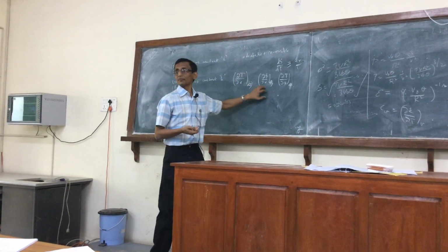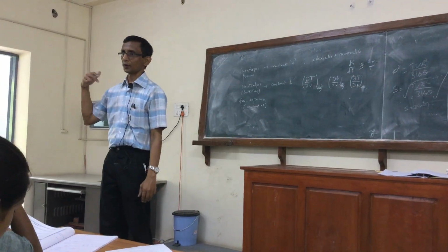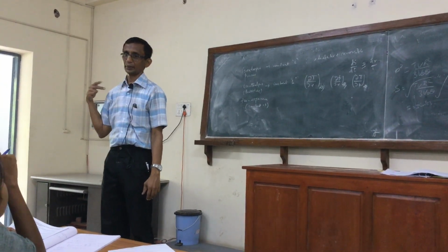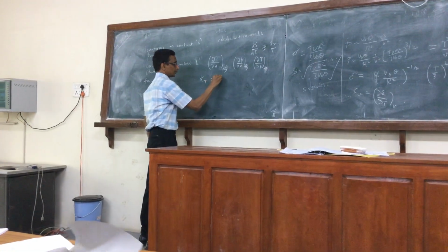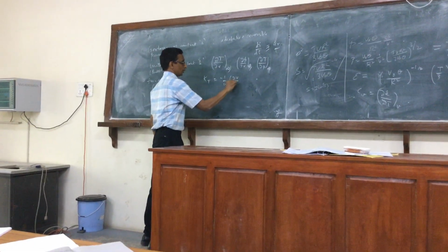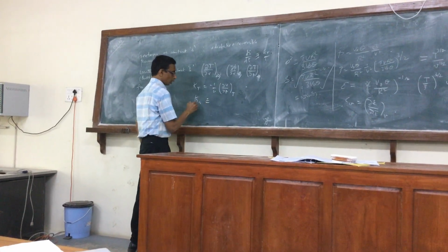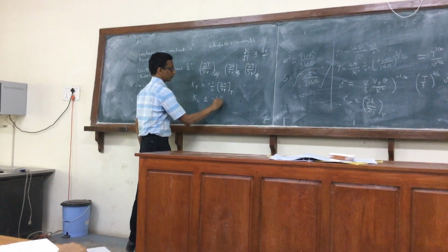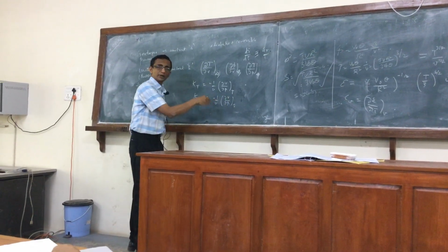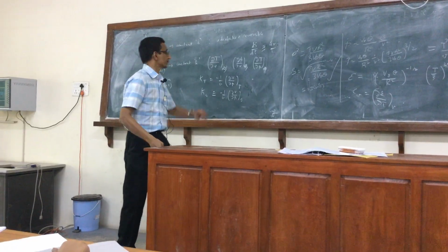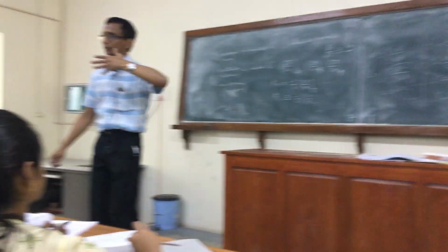dP by dt at S, we saw this in the propagation speed. This leads to what is called the isentropic compressibility. The isothermal compressibility is minus 1 over V. Isentropic compressibility is, but this is simply the inverse of dP by dV at constant S, and we've got expressions already in terms of the speed of sound and gamma and so on.